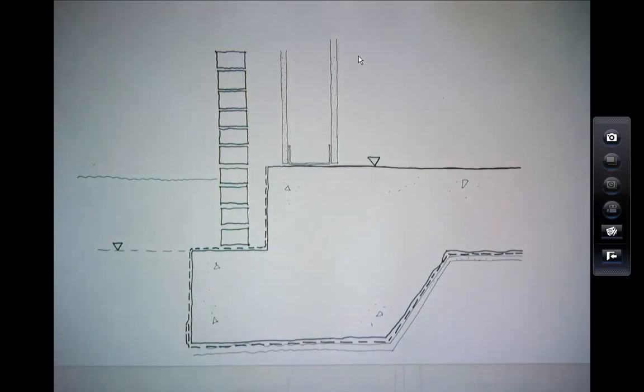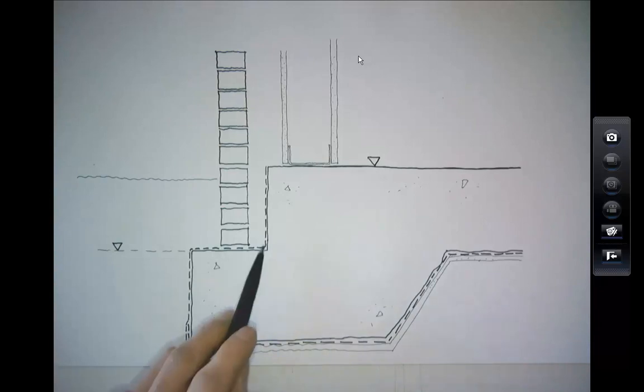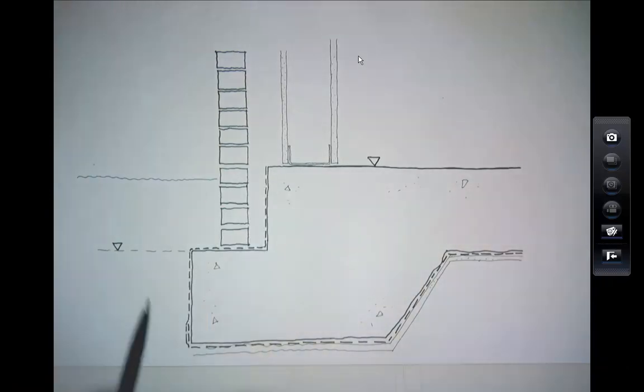So it's very, very thick, it's very, very sticky. Okay, but they literally stick that on. And where they've overlapped the membranes here, they can stick it back over the membrane that they've lapped over. And that will give you a complete intact waterproof membrane around your concrete, which is just stopping any water in the ground getting into your concrete.